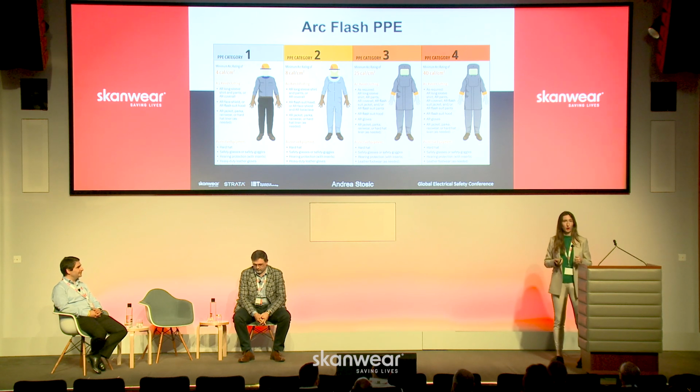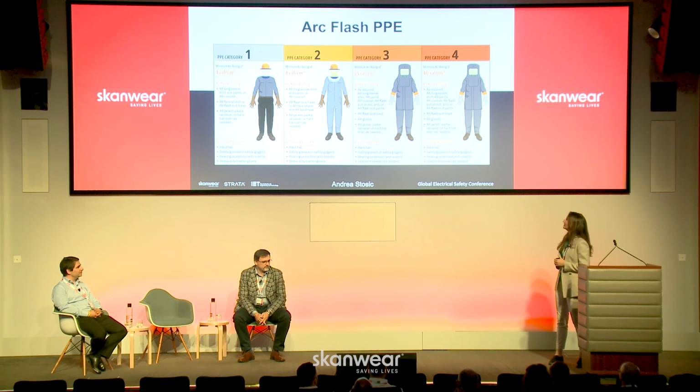Later on, when you do go out for the break, check the gloves that the Scanware team has on display. When you look at the 40 calories gloves, you will see that the glove is really thick. You have good flexibility and good movement, but your fingers do not feel as accurate as normally. And it's just important to always try to reduce the incident energy levels as much as we can, because generally the feedback from the operations team when they have to wear a 40-calorie suit is not great. It's not comfortable, they sweat a lot, they just don't like wearing it. So if we can reduce this, we definitely should.